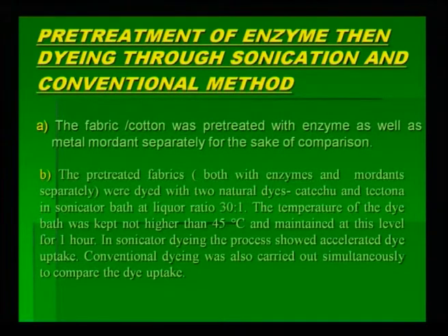The temperature of the dye bath was kept not higher than 45 degrees centigrade and maintained at this level for 1 hour. In Sonicator dyeing, the process showed accelerated dye uptake. Conventional dyeing was also carried out simultaneously to compare the dye uptake.